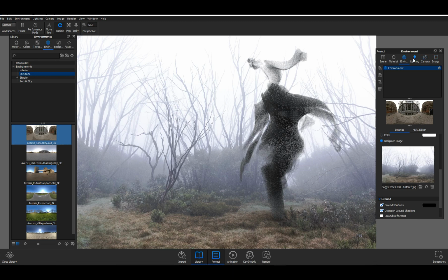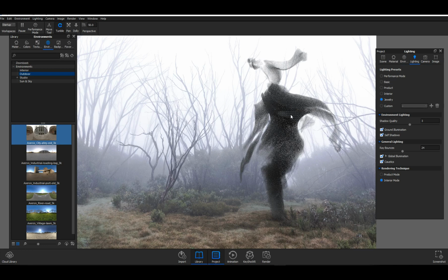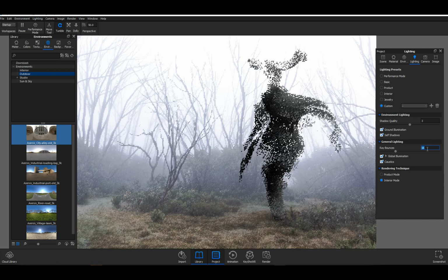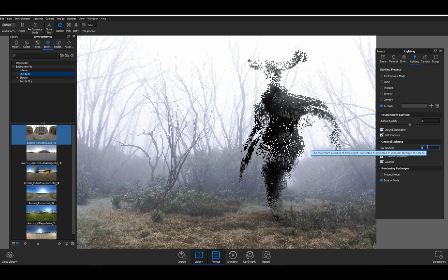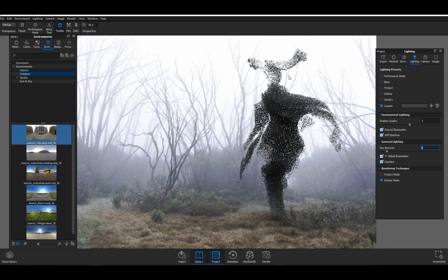You might also experience a thing where it doesn't have enough rays to bounce through the volume. So what you want to do is increase the ray bouncing quite high. I'm using this jewelry preset. Maybe it's a bit too high. I think 16 should be enough, but I think 8 or 6 will definitely produce just a black smoke, though it looks kind of fine. Maybe 6 is, well, I played around with different values. I think 6 wasn't that great.